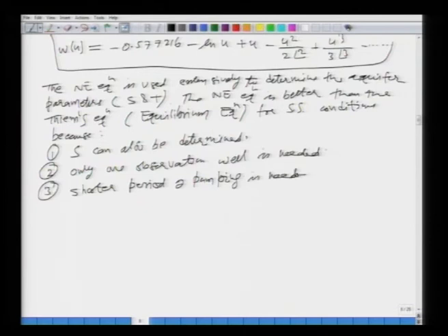Why? Because we are using it under the unsteady state conditions which are in the beginning, or as you start pumping, initially the things are unsteady. So, if you have an observation well, you can make the observation, you can note down the time and drawdown etc., and we can apply these equations. That means it is more economical as compared to using the Theis equation, because there you have to wait for the steady state conditions.